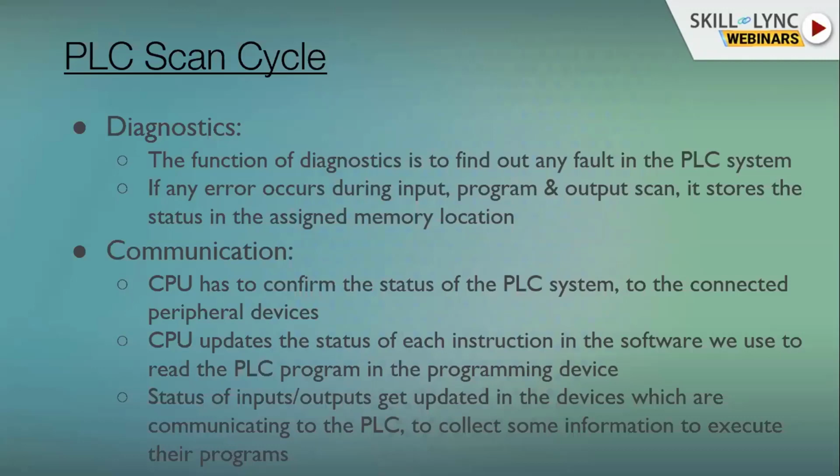Then communication, because sometimes we also need to know the status of the PLC on our laptop. In this communication scan, the processor will be updating the status of each input and output in the software we are using on our laptop. During this process, it will also be updating the status of the PLC to other PLCs communicating with our PLC.